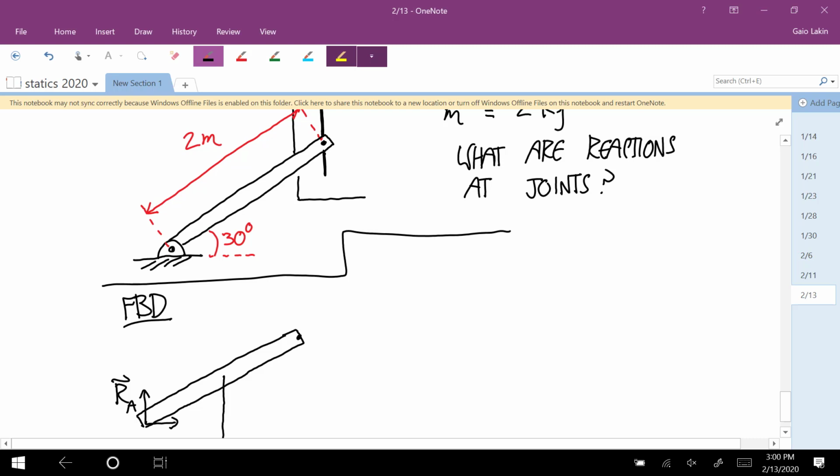What matters there for the direction of a pin and slot joint is the angle of the slot. That force is always perpendicular to the slot. So you can draw it one of two ways, either to the right or to the left. And whichever one you choose, the sign is going to come out to tell you whether you were right or wrong. It'll correct it.